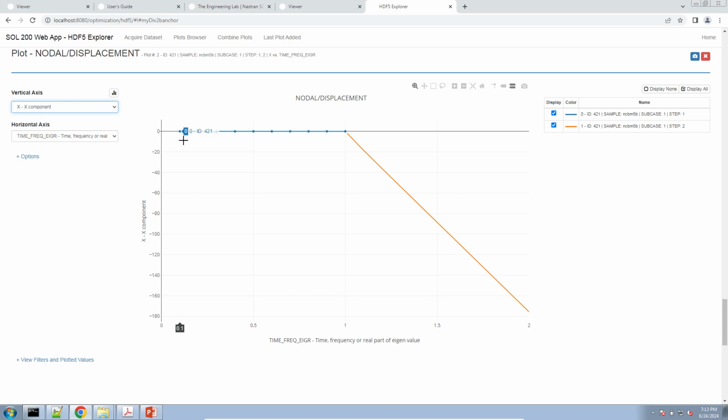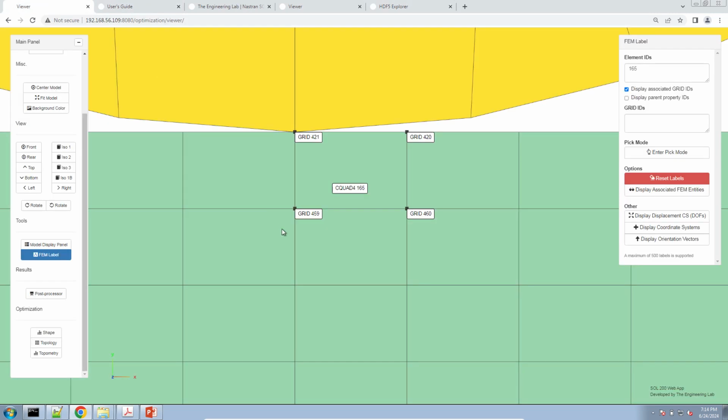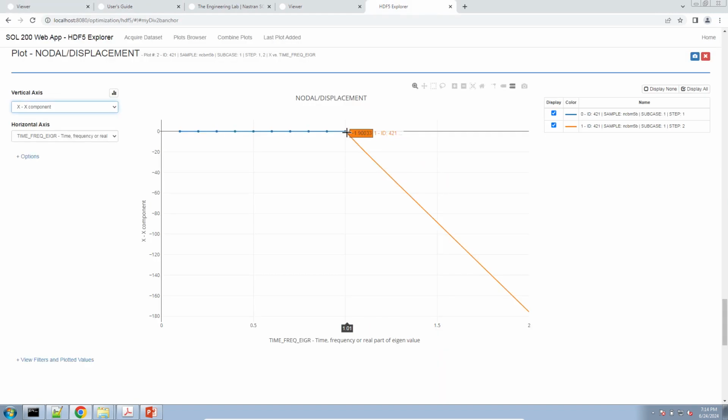So here for the first second, there's no lateral or horizontal motion of the rubber base. Remember, for the first second, we're only moving up the rubber base by 3 millimeters. Only after the first second do we start to rotate the roller. So at the very end, we get a final displacement of negative 175.7761. So let's go ahead and write that down.